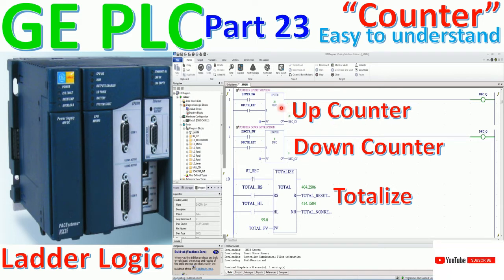It means that when we provide the input, here in the input, it will count from 0 to 1, 2, 3, 4, 5. And here you see R, it means reset. For example, if the CV shows 20 and we push the reset button, it will reset to 0. If we set 20 like this, the output will turn on when the counter counts to 20. So if 20 equals 20 of PB, then the output is turned on. So this is an up counter.